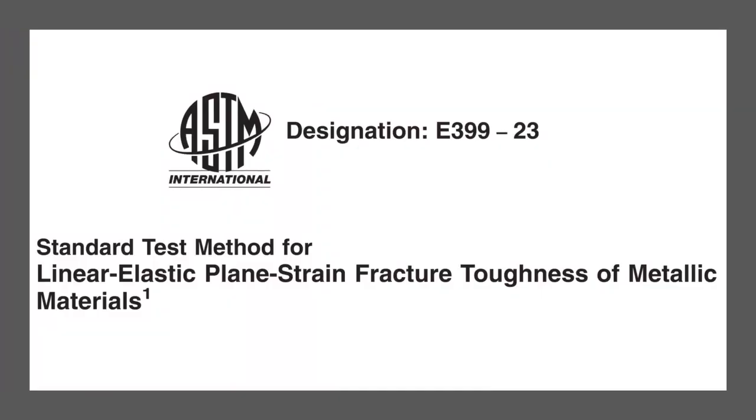The American Society for Testing and Materials standards provide the guidelines for fracture toughness testing. This standard covers the determination of the fracture toughness KIC of metallic thick plates under linear elastic, plane strain conditions.